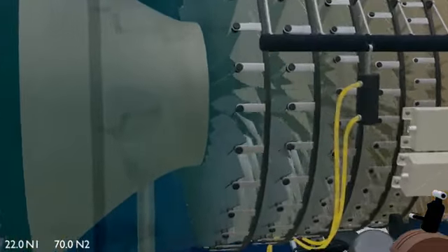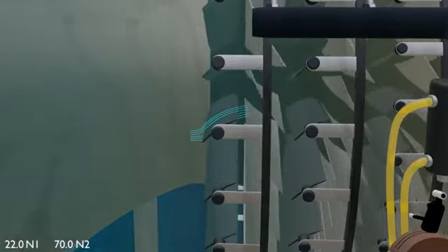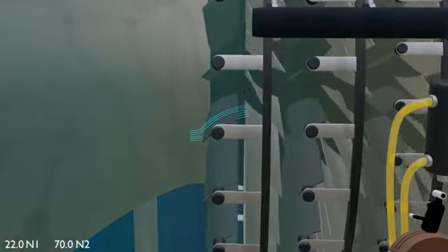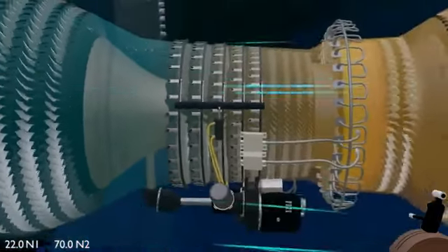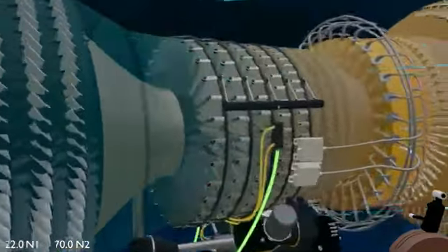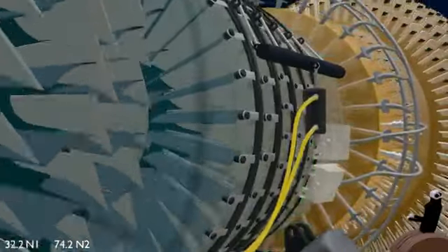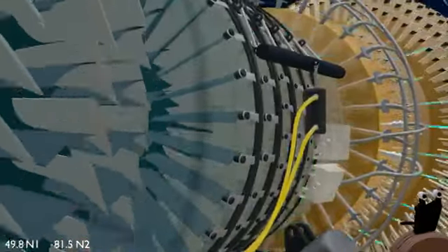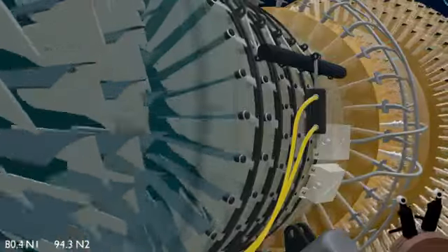reducing the angle of incidence of the stator vanes to improve the airflow into the HPC and eliminate stall cell formation. The VSV system ensures the compressor at low speeds continues to work within the stall margin. Feedback signal helps the EEC to calculate the real-time stator vane position. And as the speed of the engine is increased, the vane's angle of incidence is increased to a more open position, since the HPC is now in its performance zone with high rotational speed.